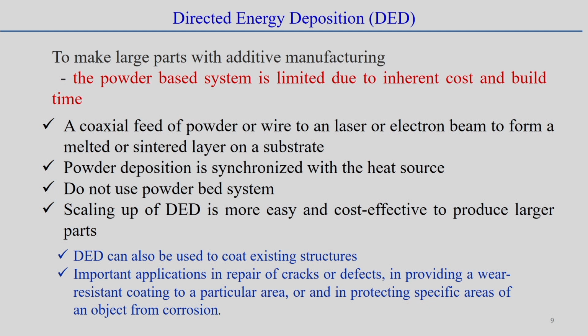Now, the powder deposition has to be synchronized with the heat source, and we do not use any kind of powder bed system in the directed energy deposition technique. Setting up DED is easier and maybe cost effective for producing larger parts, since there is no limitation on the size of the components in this case.